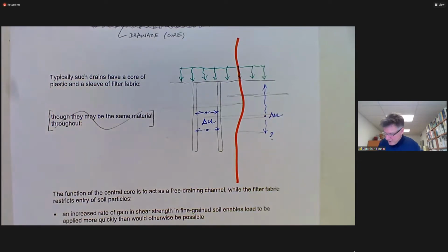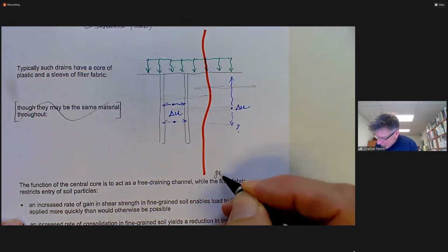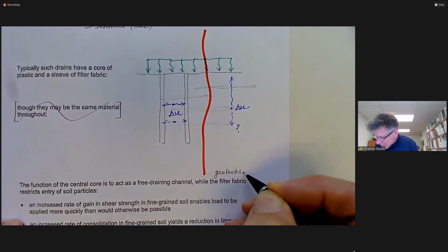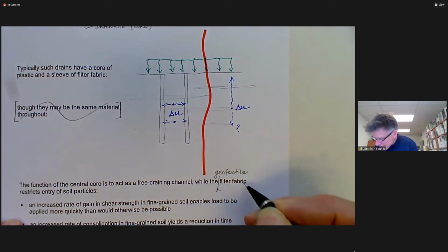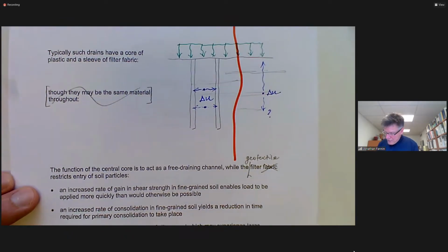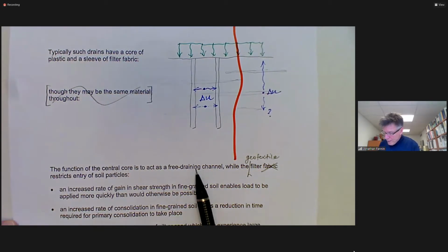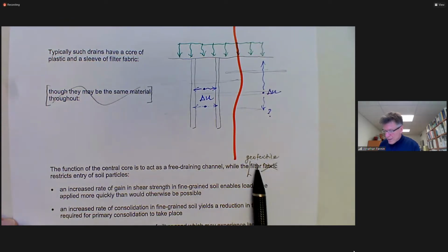You know, I should really get away from that phrase. Let's be quite correct: the geotextile filter, odds on it's going to be a geotextile. The geotextile filter is preventing the drain from clogging with material washing into it. And if properly evaluated, the geotextile filter itself shouldn't clog.